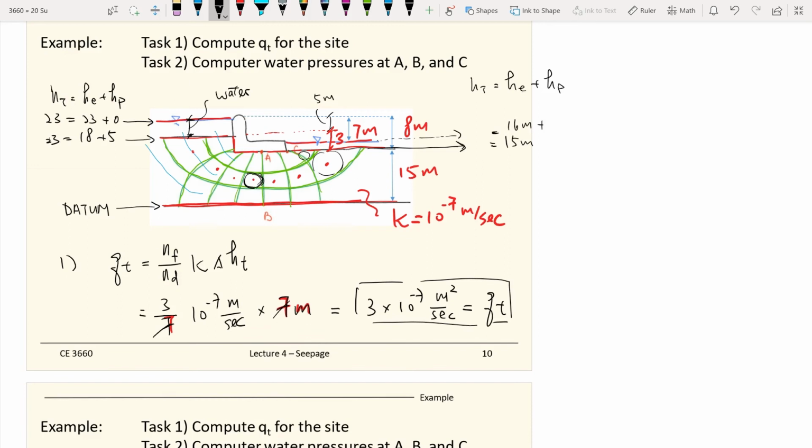And we know that now we are at the water table, so we don't have any potential head because it's open to the atmospheric pressure. So the total head has to be 16 meters. And between those 2 points again is just water, so there's no total energy loss, no total head loss. So the total head stays the same. What changes is the elevation head passing to the potential head. So they are changing between the elevation and potential. So this is what we get.